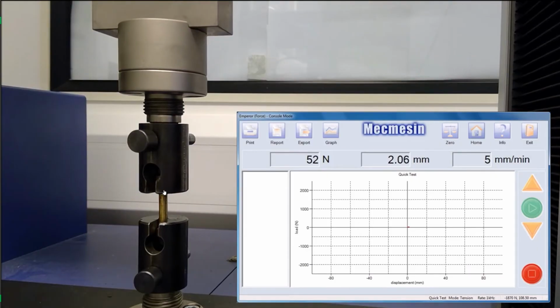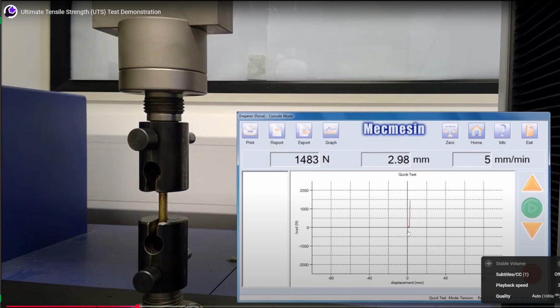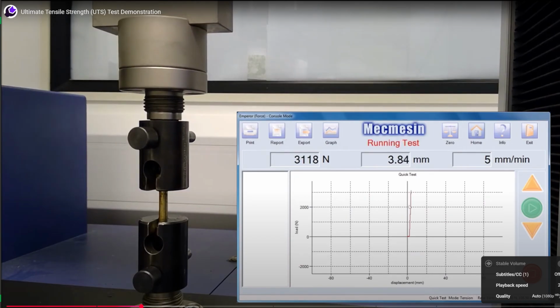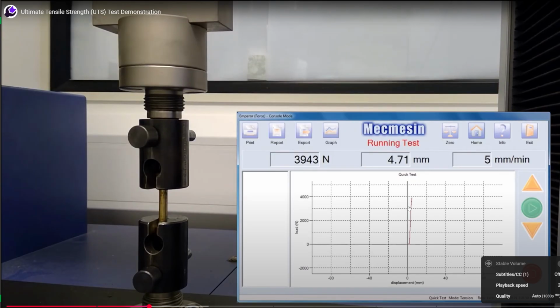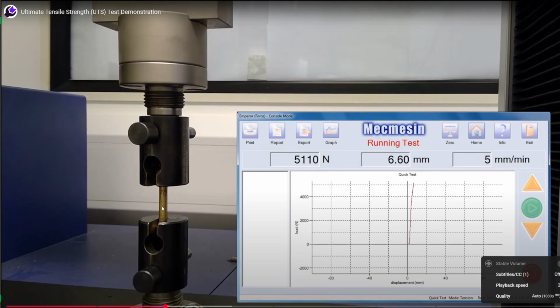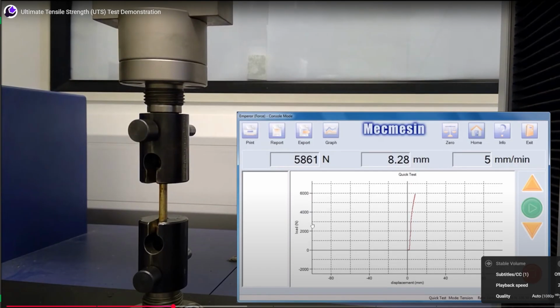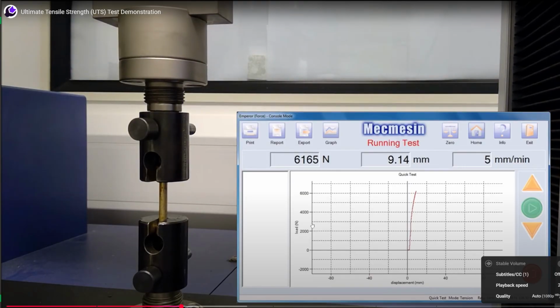Okay, anyways, if you look at the video, I'm going to move up the playback speed so it's faster. But you can see it quickly just turns into a line that's rising. I've seen this video before, but basically at about 5,000 newtons, it hits ultimate strength. And you can see that because it just starts losing it. But yeah, you can see right here, it did elongate from the beginning of the video. And right here, you can see it's also taking longer for it to increase in length because there's more resistance once you hit yield.